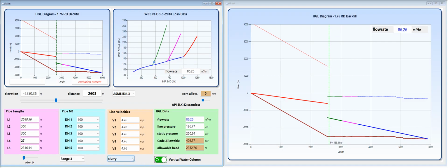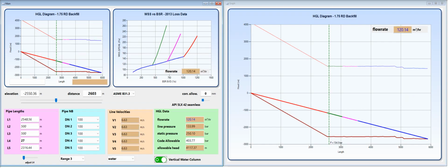And then lastly, I can just look at the delivery of water. You'll see the flow rate increases because the friction loss is a lot less. I'm not using this curve anymore. I'm using Colebrook White. Hope you found that interesting.